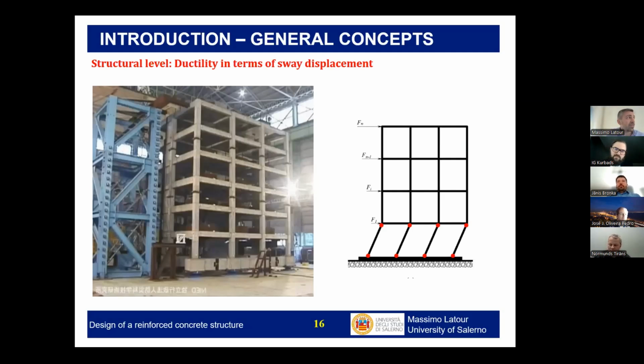So there is the possibility to design this foundation and also seismically design the building, placing equivalent springs simulating the pile, also considering the interaction between the piles. But we are going into very complex geotechnical work. There are a lot of studies about this, also with very complex discrete element methods. So it's a bit complex. But for everyday design, I think you place the full restraint and don't think too much about the foundation. You will design the foundation in the second step of the analysis.